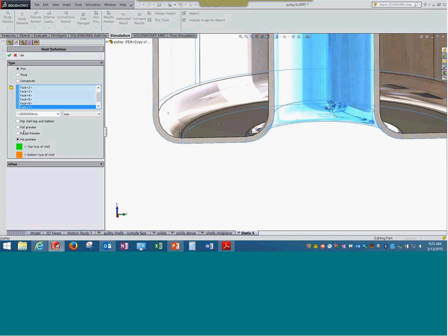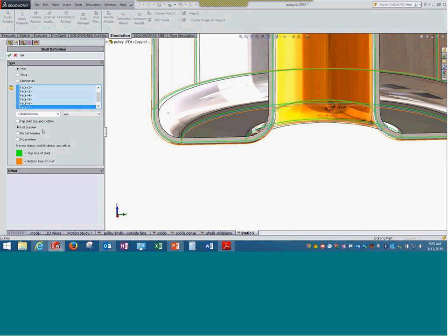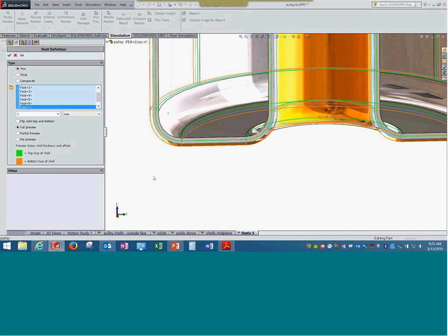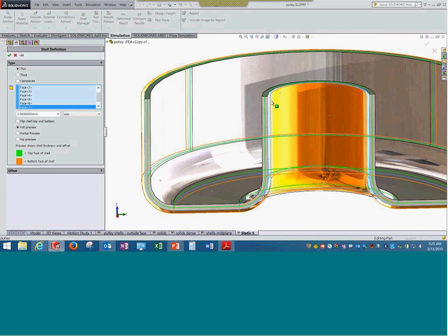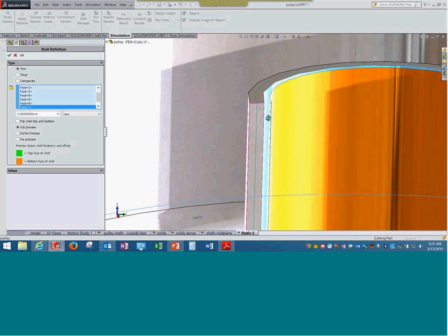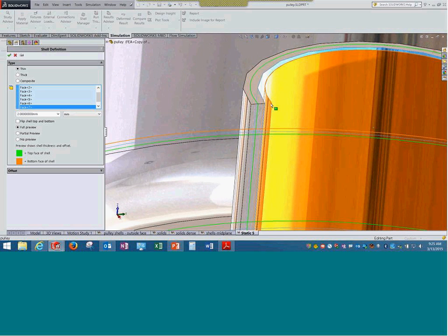Then, I do have the option of viewing it. That is, if I select this particular surface and give a thickness of 1 millimeter, actually in this case it should be 2 millimeters, how exactly would it be placed internal to the software? So this is not visualization; it is more for calculation. So obviously you can see if I select it, it is going outside. It does not make any sense. I would like to have it appropriately. I can go here, offset.